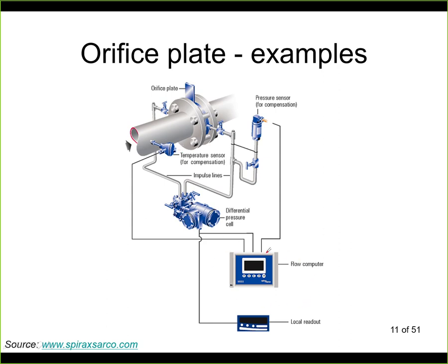Here this is called the flow computer, and it takes in the differential pressure, density, and eventual ambient pressure, and based on the equation that we've seen, it can calculate the actual flow rate.